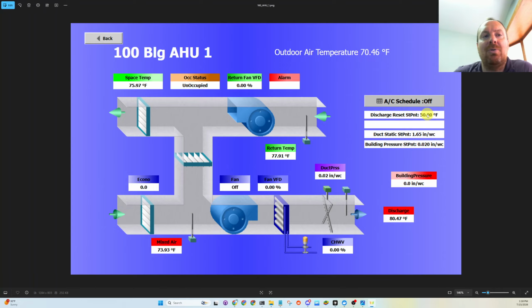So two things I'm finding in this building: the economizers have been disabled. They use the air cooled chiller starting at about 40 degrees outside air temperature. And the energy saving strategy that I think I'm finding, the most ideal scenario, is fixing these economizer dampers and trying to put this. Let's see if I can find the chiller one.